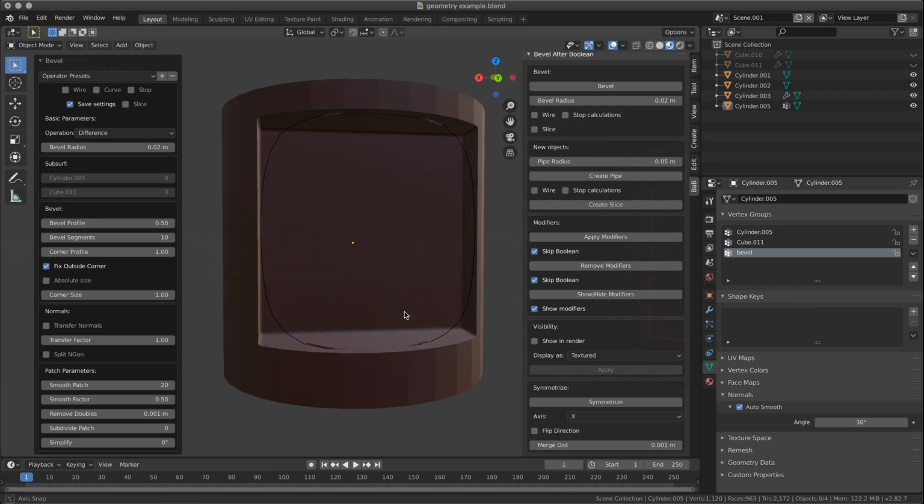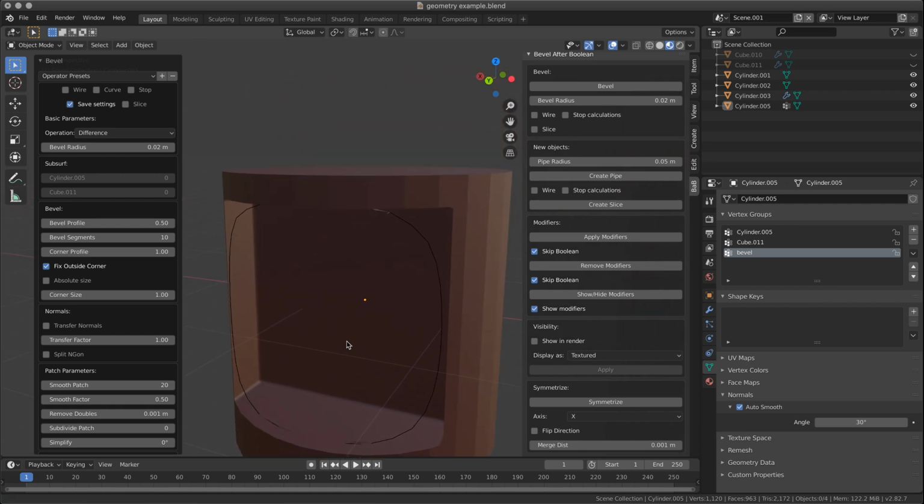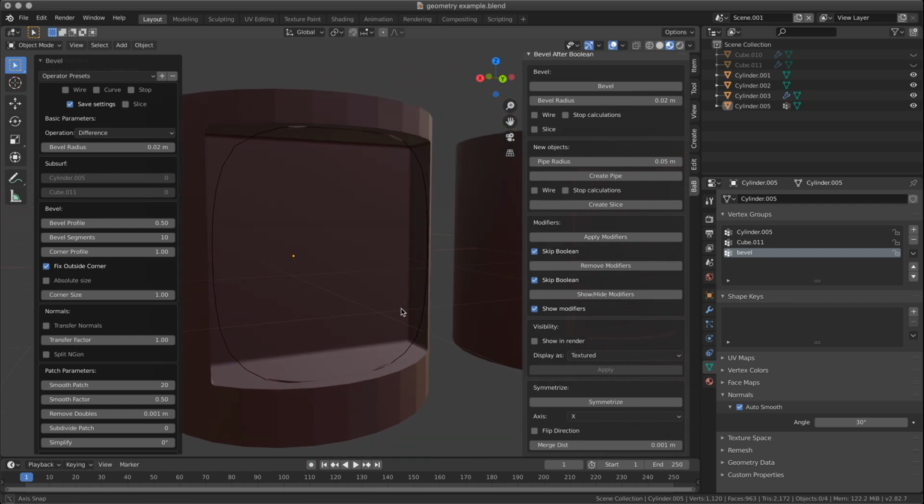This plugin is very powerful. It's also not, for me at least, very intuitive to understand what these things would do. Turn off the subdivide patch to 2. Oh, you know this plugin so well. Subdivide patch to 2. So I'll put back the smooth to none and subdivide patch to 2.